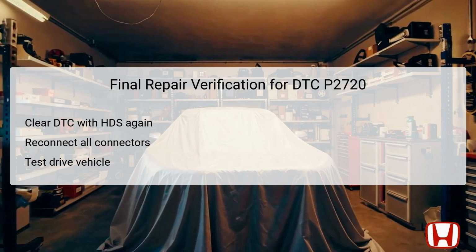A thorough test drive should then be conducted, simulating various driving conditions to confirm that the transmission functions as intended without triggering any DTCs. Observing how the vehicle operates during the test drive allows the technician to assess the effectiveness of the repairs and ensures that any previously existing symptoms, such as erratic shifting or loss of power, have been resolved. Successful verification signifies that the repair process was effective, providing confidence in the vehicle's reliability.